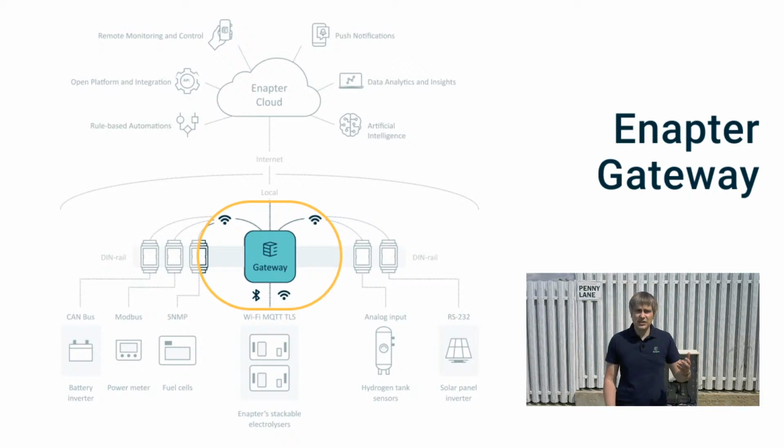The rule-based engine is a very unique tool, which allows system integrators to set up their own custom if-then-else logic according to the needs of the customer. For example, for our setup, we can make the rule to switch off energy output from battery to grid if voltage on battery is dropped below 25 volts. This will help to save the battery life from full discharge.